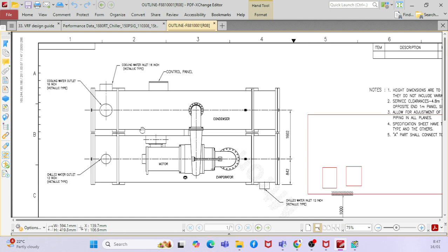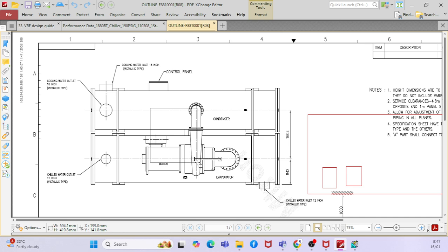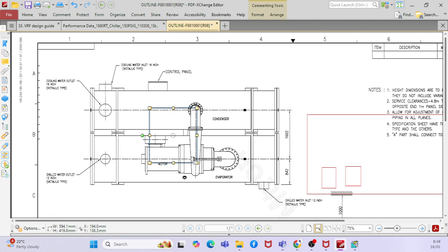This is the refrigerant cycle, and this is the centrifugal compressor. The centrifugal compressor is a part of the refrigerant cycle, where you have a compressor, expansion vessel, condenser, and evaporator. There is a refrigerant circuit here, where the refrigerant will cool the water, and that refrigerant will dissipate the heat through the condenser. The condenser will take the water from here.